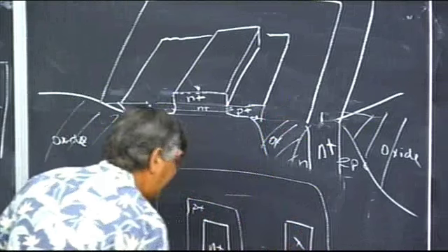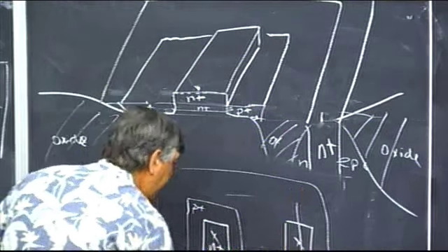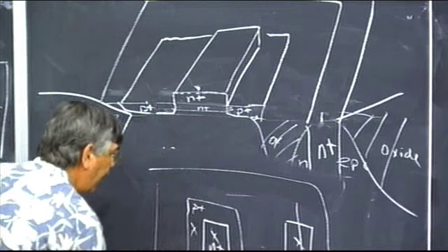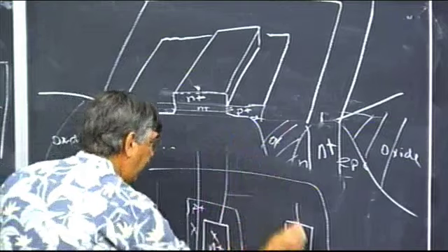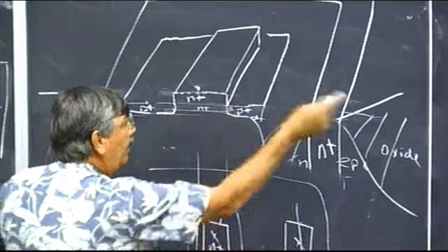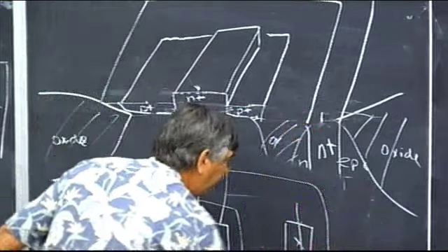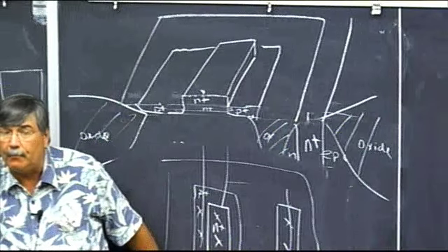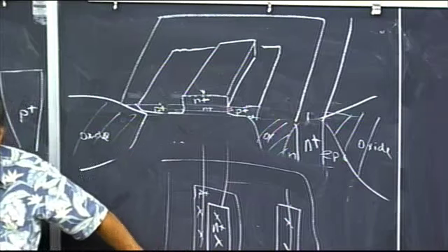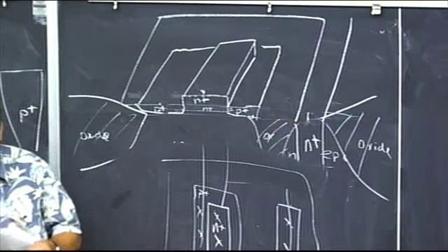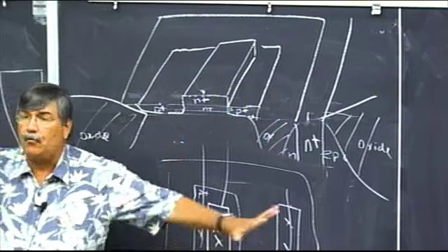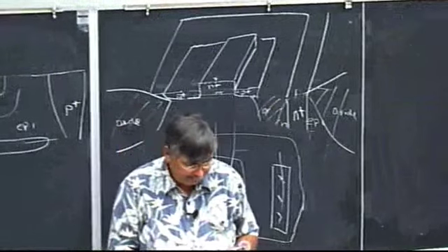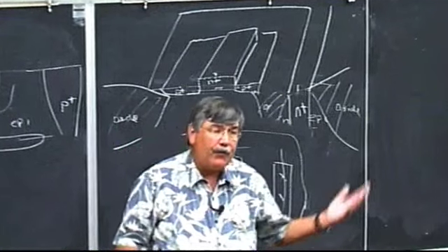So we'll put metal contacts here, and there needs to be room for contacts here somewhere as well. All right, and we'll run wires off for those. And somewhere not even shown is a connection to the substrate outside. The substrate's common to the entire chip. That's an important point. The overall substrate of the chip, remember it was whatever, P-type stuff. That's the whole chip. Physically, it holds everything together. Everything is in that substrate. Okay, so that's a typical design.